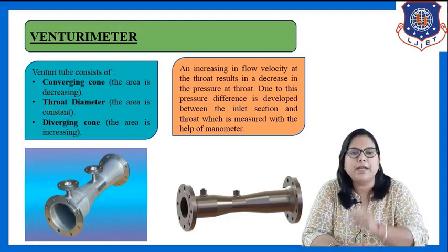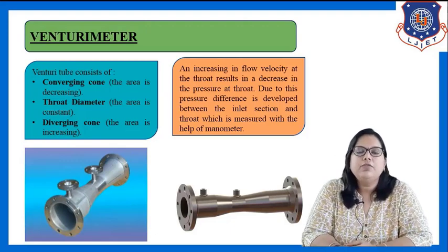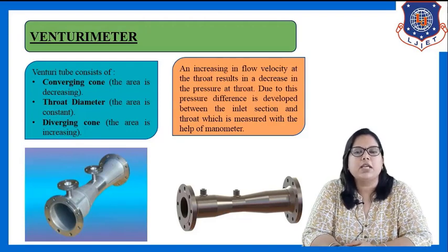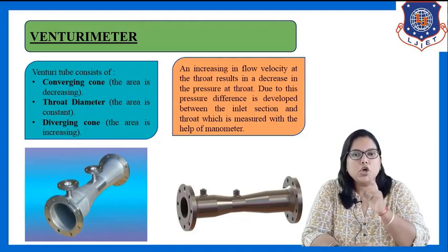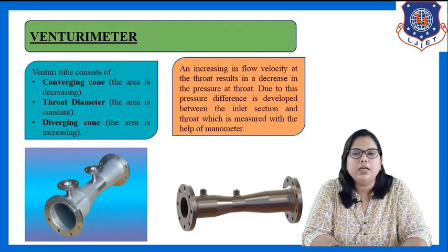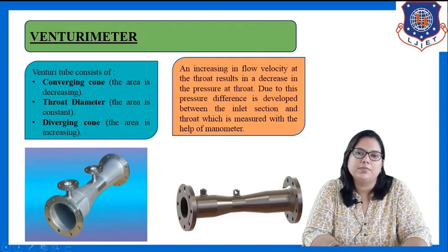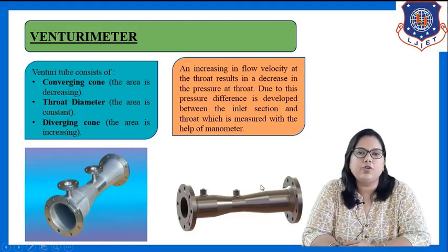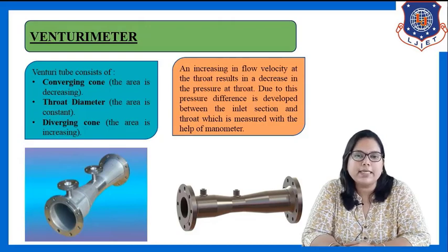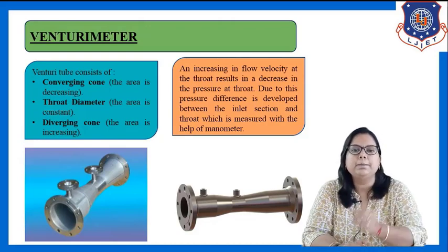Due to this pressure difference, we have to measure it with the help of a manometer. So here we installed a manometer, and with its help we are going to measure this pressure difference, which is created between the inlet section and the throat section.